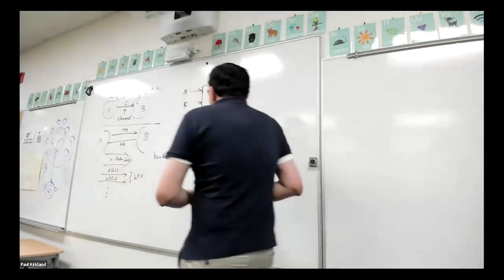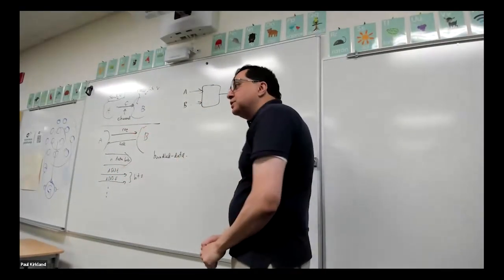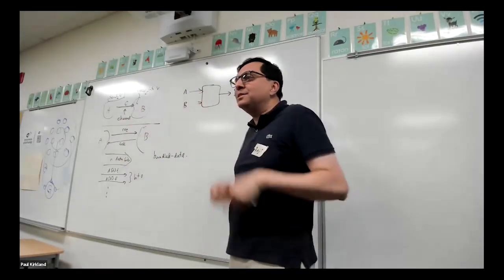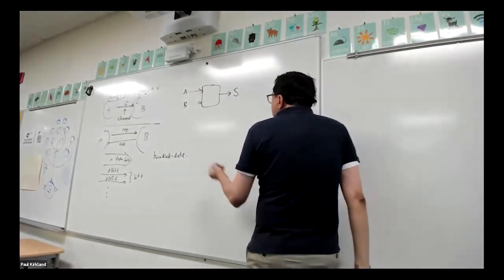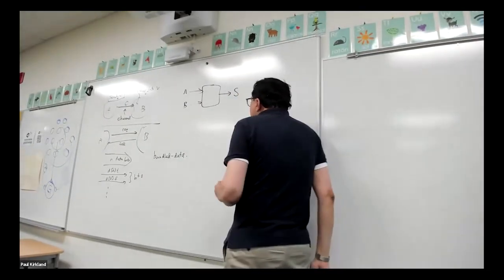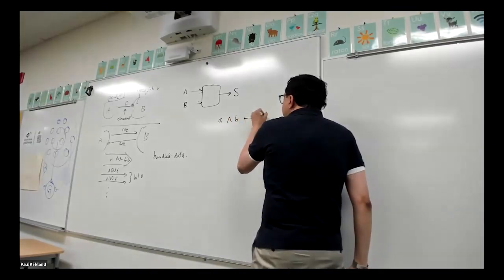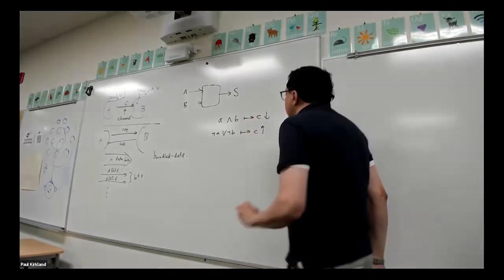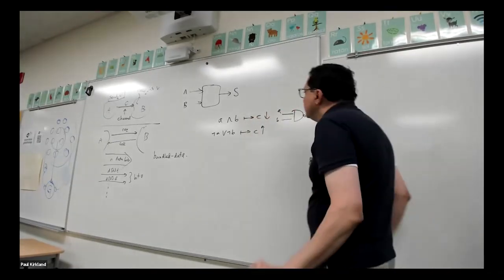Okay. And so the target language we use tries to be as close to gates as possible. So this is my object code or assembly language. If you're a software developer, it's more like the assembly language for my chip design. And the syntax we use looks like this. So I'm going to show you a NAND gate. So this is a NAND gate with C at the output and A and B as the input.